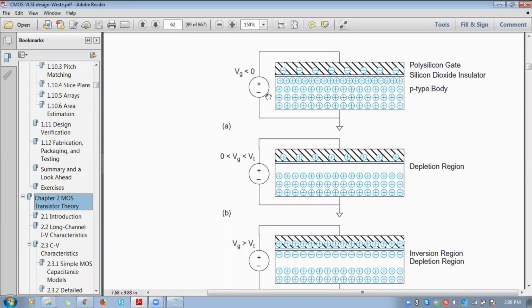If the manufacturer is using silicon, then the threshold voltage ranges between 0.6 and 0.7. If we are using germanium, it ranges between 0.2 and 0.3. There are a lot of parameters which affect the threshold voltage that we will see in the non-ideal IV effects. So here, what is happening is we are applying a small positive potential to the gate.